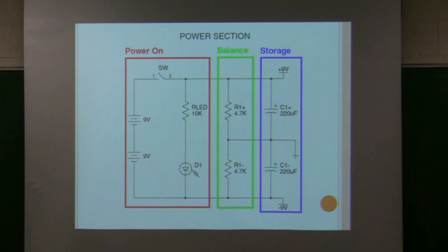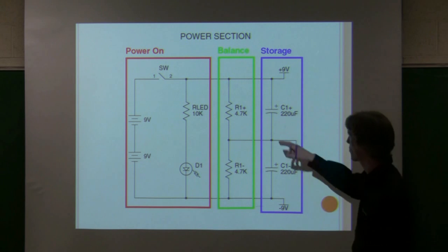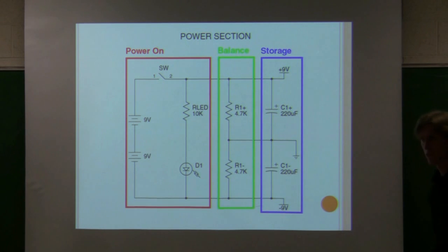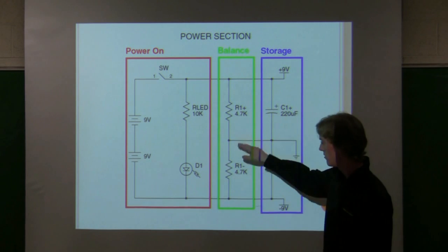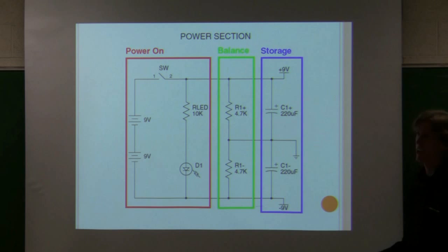And so if you think of voltage, it's a difference of two voltages, right? So if you say 9 volts, what you're really saying is, well, I have 9 minus ground, or 0 volts. The trick that this circuit plays is from here to here you have 18 minus 9, which gives you 9 volts, right? That's your positive 9 volt supply. From here to here you have 0, and then you have minus 9, so you get minus 9 volts.